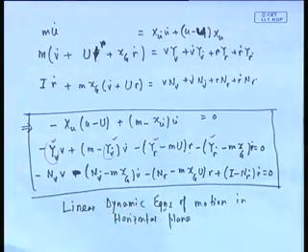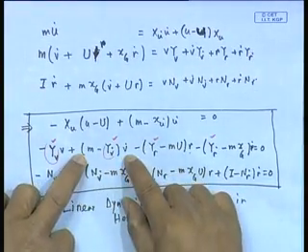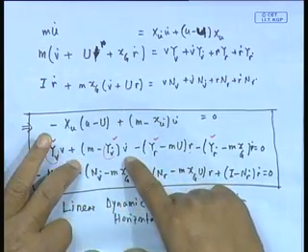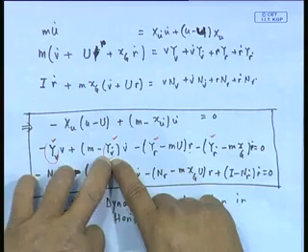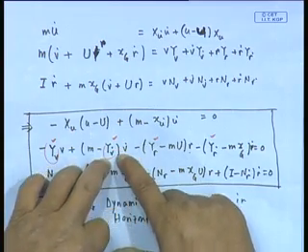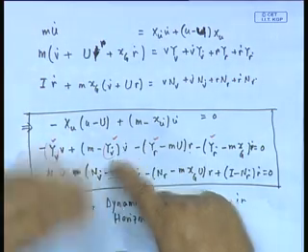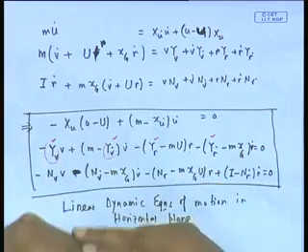I want to close with your analogy. See this first term, m minus Yv dot, times v dot. Just see this term, then I will end today's class. Now in the equation of motion in seakeeping, what did you find? Mass plus added mass into acceleration. Here I am finding mass plus minus Yv dot into acceleration. What is then Yv dot? It is nothing but added mass with a minus sign, because what is this Yv dot times v dot? If I accelerate the body in the direction v with a v dot, it is the amount of force that gets created.